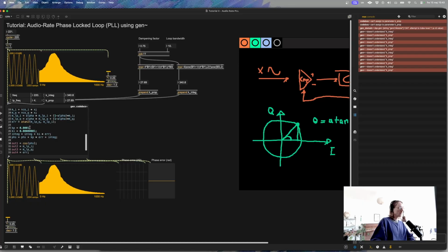And then we can set kp, which is this constant that we computed, but also divided by the sample rate, and ki will be k integral, our parameter that comes in, divided by the sample rate to the power of 2, like that.